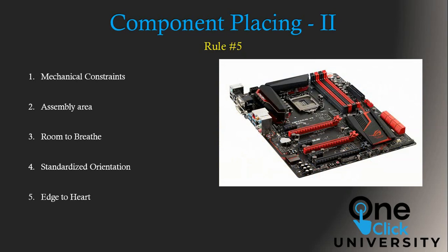And finally, number 5. This one is the last tip from my side, the one tip that's too obvious to even pen it down. First, place the components that are close to the edge of the board, such as the power jacks, the power sockets, ports, etc., and then place the components slowly towards the center that may include the processor or the controller.